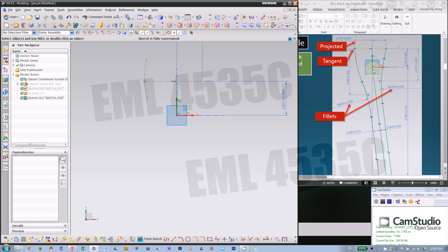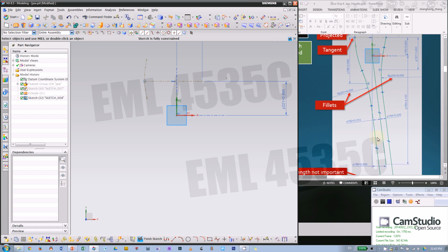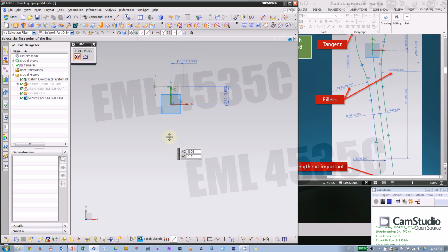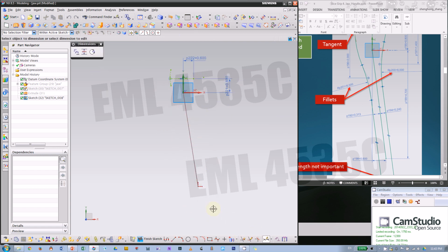Okay, and now we can start this shape. We need to start from the middle. Okay, if you see those parallel. Alright, so we have a line in the middle. That's like the direction of the handle. And we'll give this an XY dimension. So the vertical dimension is 4.7 inches. And then horizontal dimension is 0.6 from y-axis.